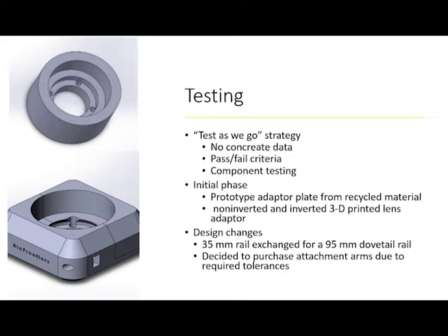designing the tube lens adapter, in which we initially made the first one, which is the picture on the top left. What we realized with this adapter was that it was too wobbly, and we didn't want to risk the stability, because when you're looking at a mechanism under the microscope, it has to be super, super still in order to create a nice clarity picture.